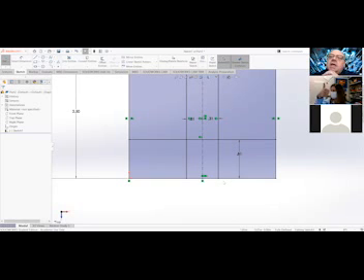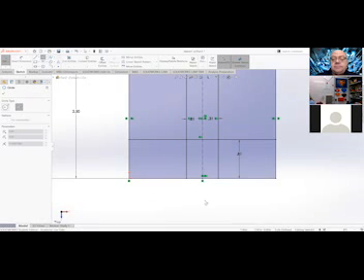So when we did it in AutoCAD, we ended up having to move it down from the quadrant to the right position. Let's go ahead and go to our circle tool and hit that little down arrow to the right of it. And we're going to do a perimeter circle. In other words, we do tangent, tangent, tangent is what we're actually going to do. So select perimeter circle.